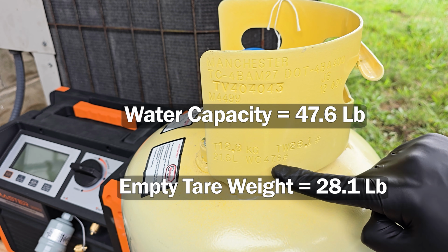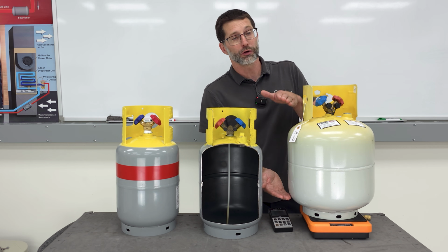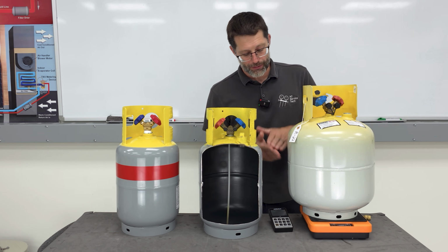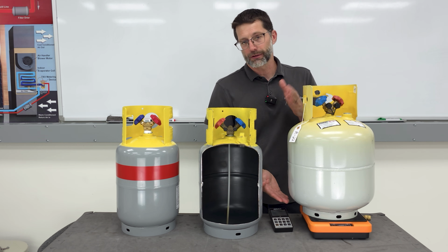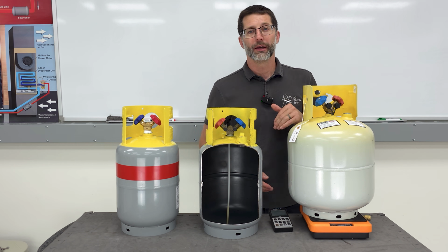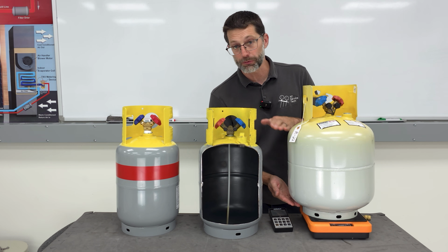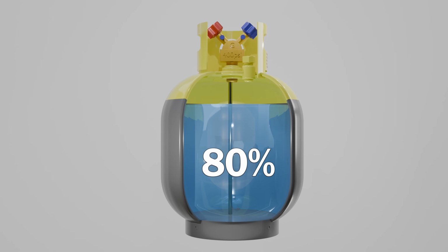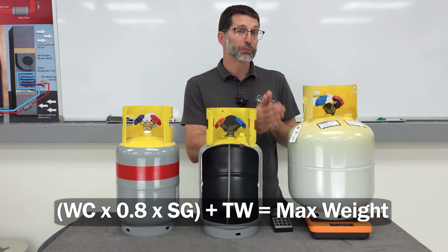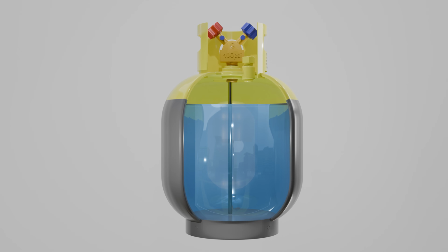So water capacity is the full amount of, say, liquid water that you could fill in the tank, and of course we're not using water, the manufacturer's using it for calculation purposes. Tare weight is the empty tank weight. And so what we do to make sure that we're only filling this up to, say, 80% or less of the liquid capacity worth of refrigerant, we take the water capacity times 0.8, that's 80%, and then we times that by the refrigerant specific gravity.